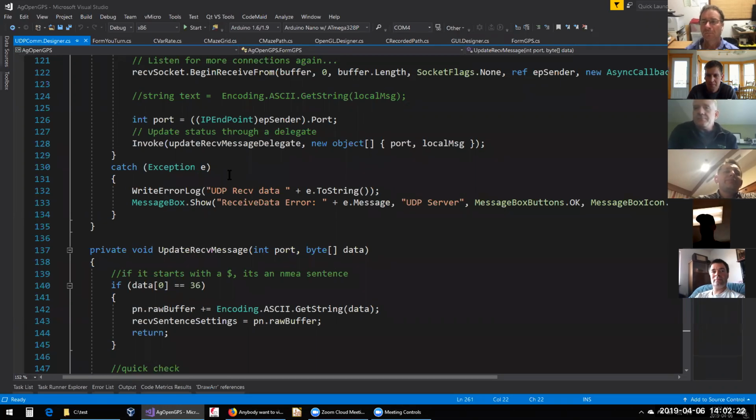Yeah, I've just got some of the cheapy $10, $12 plastic cases, and I have a bunch of those too. It'll work for now. Yep. I've ordered that relay switch input board as well, and I've ordered all the parts for it. There's some fairly small, again, automotive relays, 12-volt relays. They're really small and they're 20 amp relays, and they're just a few bucks a piece. It's an incredible relay from DigiKey. So looking forward to seeing those as well. That should be providing good power. And then using that ULN2803, it'll drive all those relays no problem.